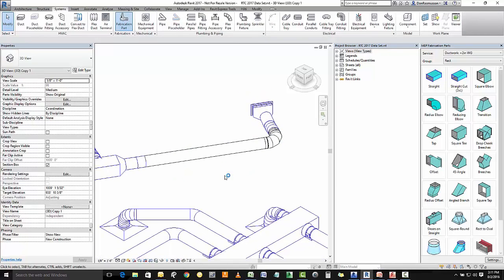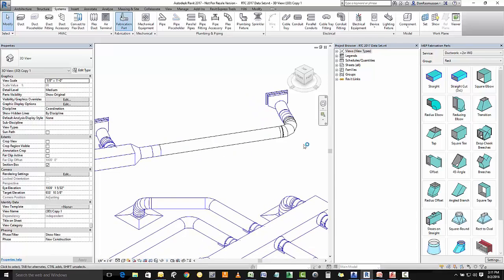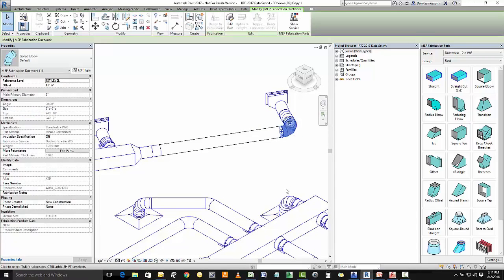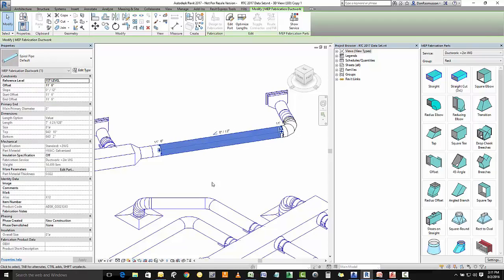But now here's a couple things that I want you guys to keep in mind. These pieces here are fabricatable pieces, so that makes them ITM content. And ITM content used to solely live inside of the fabrication suite, but now we're introducing it into Revit. But what it does mean is that these aren't RFA families. They aren't going to have the amount of parameters that you would like. You're not going to be able to input even your own parameters.